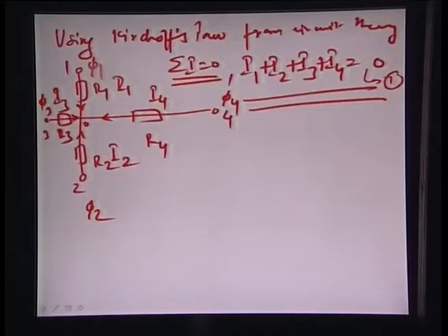We also try to figure out what the differences in potential would be. So if you look at, let us say, just the arm 4 to 2 and 4 to 1. Okay. So phi 4 minus, let us assume that there is a potential phi 0 at this particular node here, right. So we can also write this as phi 4 minus phi 0 is essentially the drop in potential by assuming that I4 passes across the resistance R4.